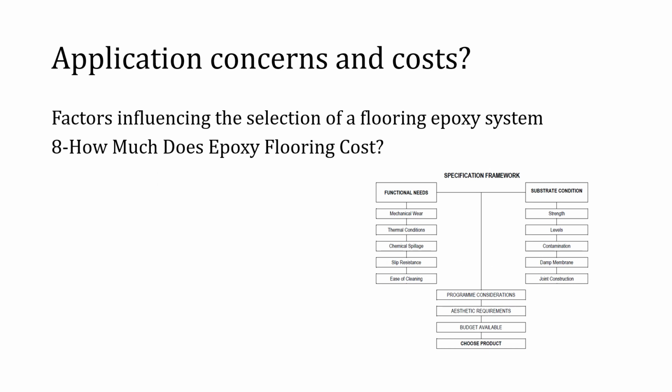Different resin types give different combinations of application characteristics and in-service performance. Factors influencing the selection of a flooring epoxy system include type and degree of traffic, temperature to which flooring will be exposed, nature and duration of any chemical contact with the floor, wet or dry service conditions, slip resistance requirements, statics, ease of cleaning including hygiene requirement, moisture content of the substrate, time available for application and cure, prevailing site conditions at time of installation, and finally the cost.